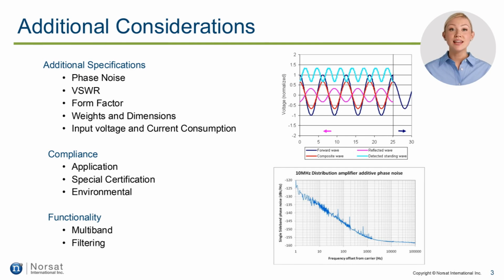For mobile applications, where a satellite terminal needs to be transported around the world, they might use multiple LNBs depending on the region they are going to be used in. An alternative is to use LNBs with multi-band capabilities. These LNBs have the ability to switch between multiple LOs within the same unit through the input voltage, normally 13, 18, or 24 volts, in combination with a tone, usually a 22 kHz tone.